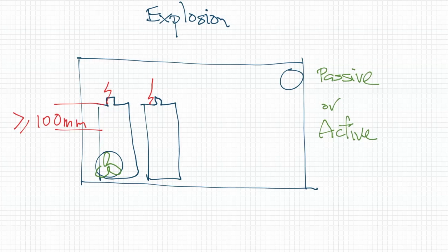Yeah. Now, we've got this strange relationship with the National Construction Code. It used to be called the Building Code of Australia. New Zealand's got a different one. The National Construction Code does actually refer to batteries in buildings and has a very onerous requirement for any battery system of more than 20 amp hours and 12 volts, I think it is.